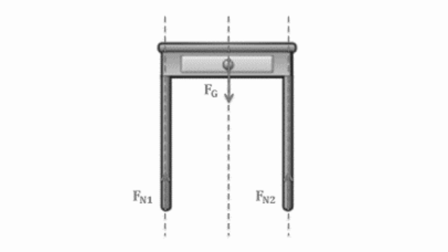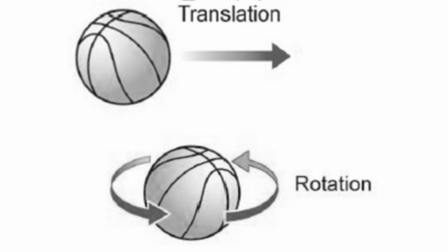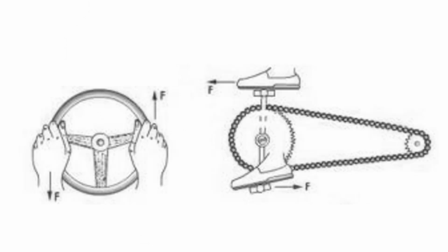The main difference between concurrent and non-concurrent forces is that if they are exerted over free bodies, the first ones can cause translation movements, the body moves to somewhere else, whereas the second ones can do rotational movements, the body turns. For example, when driving your hands are opposite each other on the steering wheel. The forces you apply with both hands when turning either left or right cause it to turn. Both hands are involved in turning the wheel, one hand pushes while the other pulls.